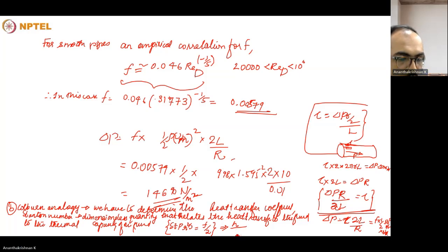And then m dot Cp divided by area, we can write as rho into velocity into Cp. Prandtl number is mu by alpha. We need not write it; we can actually calculate the Prandtl number. That's a property of the fluid at the temperature. So Stanton number into Prandtl number raised to 2 by 3 is equal to friction factor by 2.